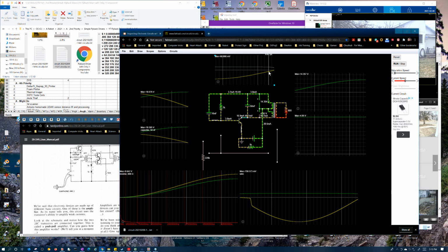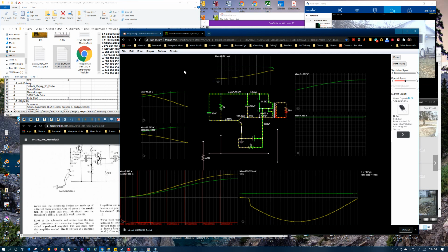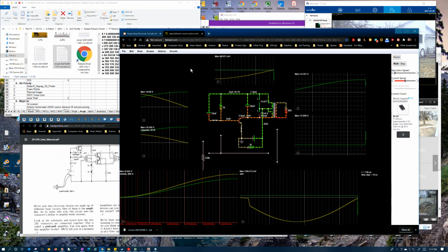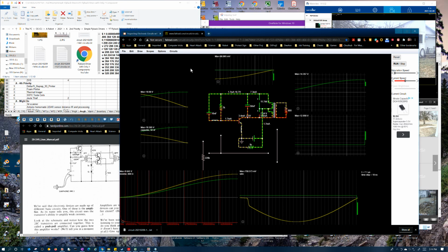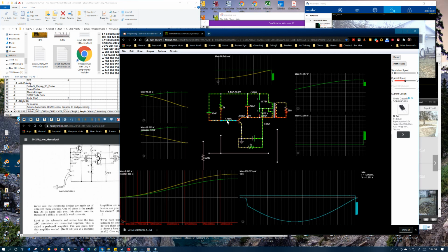Here you can see the base current is almost zero now, and the collector voltage is dropping precipitously. Okay, now it's just gone into kind of an undefined state, because we're down to almost no current and there's very little flowing here.